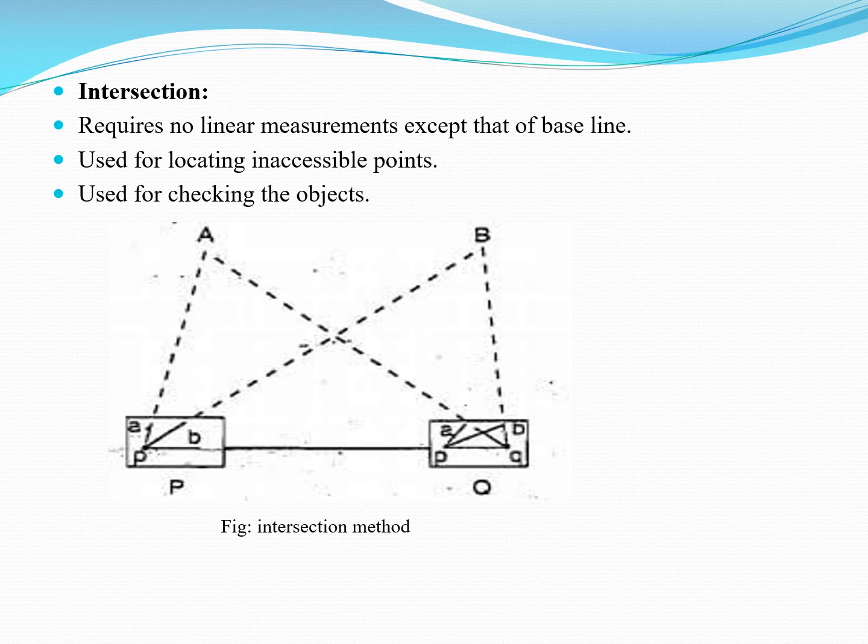After that, the alidade touching point Q, objects A, B and point P are bisected and the rays are drawn along that alidade, and the plotted rays are intersected at the 2 points A and B, which indicates the position of inaccessible points on the ground.